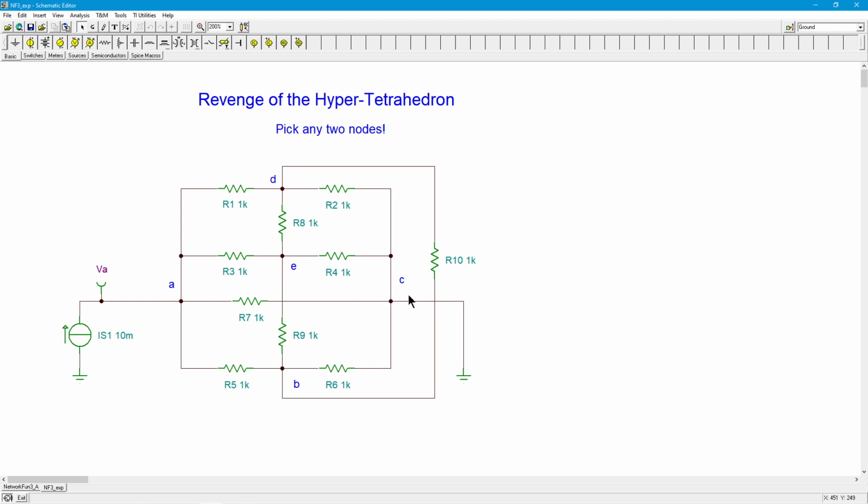If I chose the current source to go into node D and the ground was, let's say, on node E, what ends up happening? Well, R8 would be analyzed kind of the way R7 is. That would be the sort of odd guy out. And then you would have an appropriate combination back here. So you would have to go through a couple of things to get to ground, just like here. It would be the same sort of result.